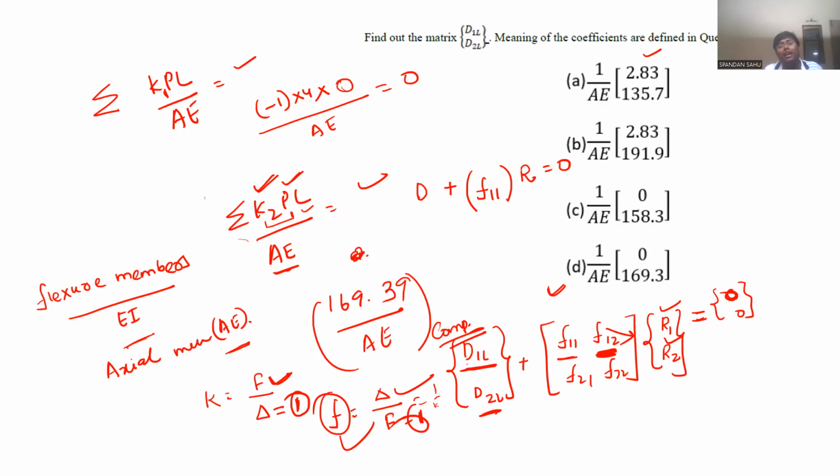Similarly here, when fabrication is going on, the machine is producing the parts. There might be some manual error or machine error, many kinds of error. The machine can make an error and you get some change in length. That was unintentional. But when you go to pre-stressing, you insert tendons, jack them at both ends and apply some force. That was intentional.